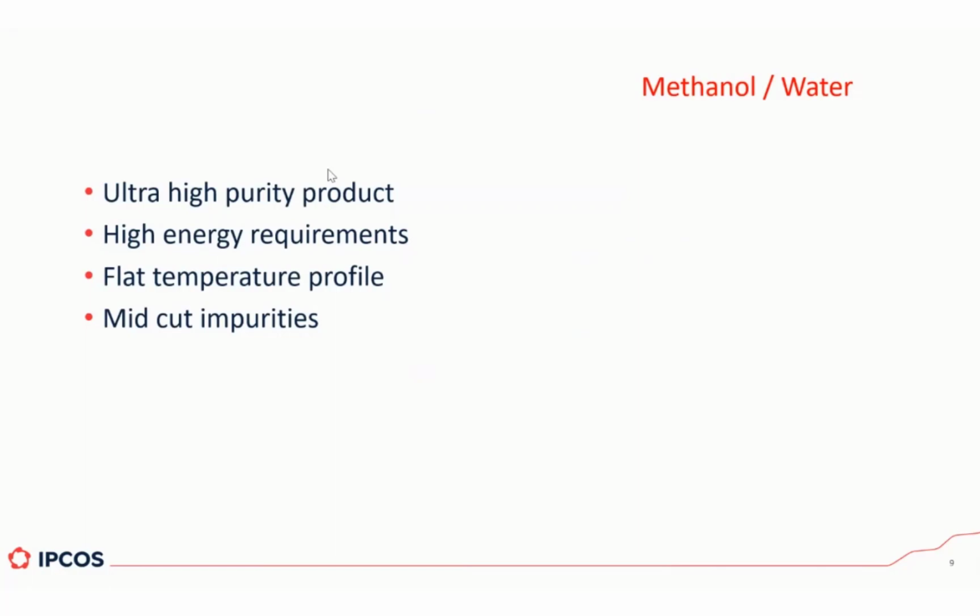So there's a steam reformer that produces syngas. The syngas goes through a catalyst in a synthesis loop and converts that syngas, basically carbon monoxide and hydrogen, into methanol and water, and there are some byproducts, and that's also where it gets a bit more complicated. Because this was a very high purity specification for the product, that's when it became really challenging.